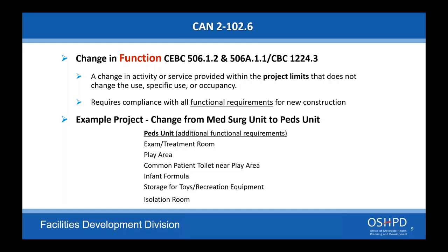Now, turning that around a little bit, say you're just going to replace a cooling tower that hasn't failed yet, but might be getting old, and you're considering replacing it. Again, the scope of the project is replacing that tower. You're still going to have the same seismic requirements and anchorage requirements to do so. And anything affiliated with that upgrade can be done as part of that project. But what it won't do is trigger additional work beyond that. And that's what we're trying to emphasize here.